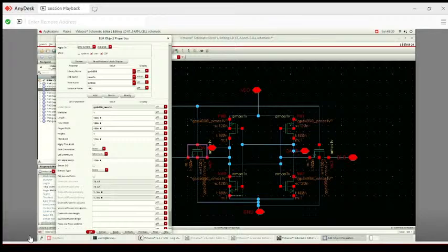So let's move to the last sizing, of the pull down transistor. So the pull down ratio should be 1.5 times, which is the width of NMOS divided by the access transistor. So the access transistor is given, which is 180. 180 into 1.5 times, so it should be 270. So let's set it to 270 nanometer.